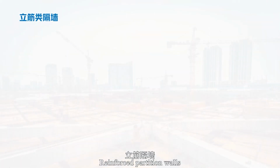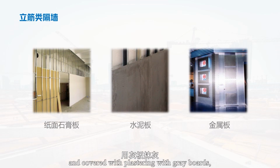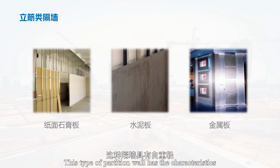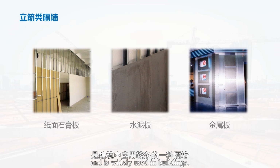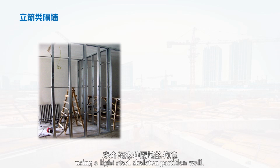Reinforced partition walls are generally made of wood and thin-walled steel as the skeleton, and covered with plastering with gray boards, steel wire mesh, paper-faced plaster boards, sound-absorbing boards, or other decorative panels. This type of partition wall has the characteristics of being lightweight, having a small footprint, and being convenient to decorate, and is widely used in buildings. We will introduce the construction of this type of partition wall using a light steel skeleton partition wall.